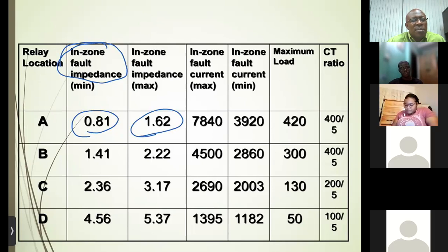Excuse me, sir. Can you hear me? Yeah, my internet went as you explained the 0.81. You can repeat it, please. That is with both transformers in place. So with them in parallel, the total MVA would be 150. And so the 0.81 would be V squared over S. So we get 11 squared over 150.